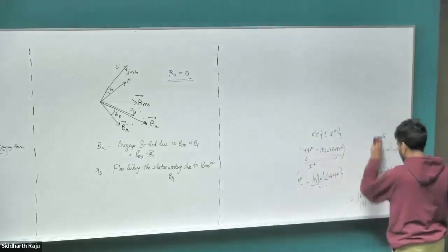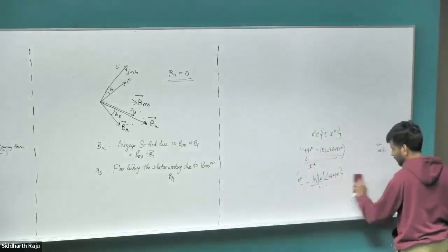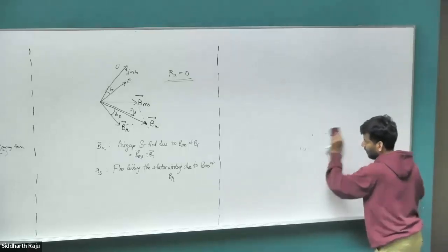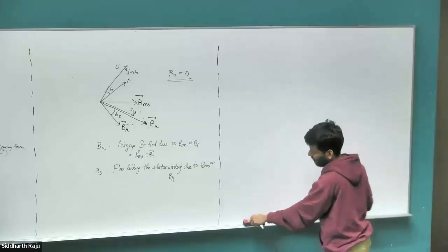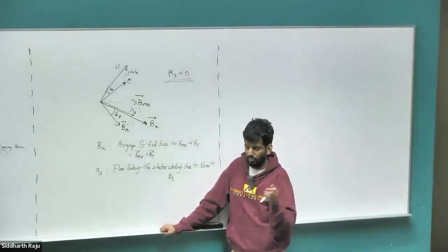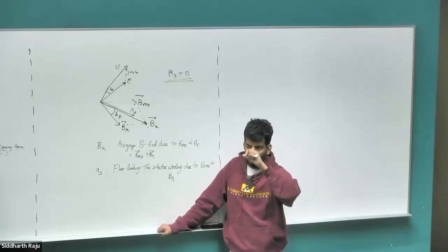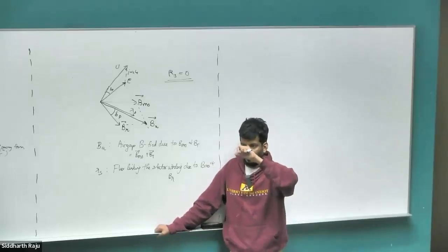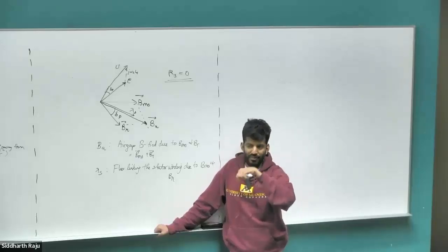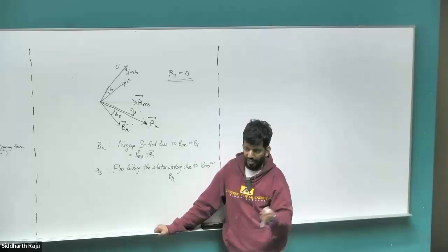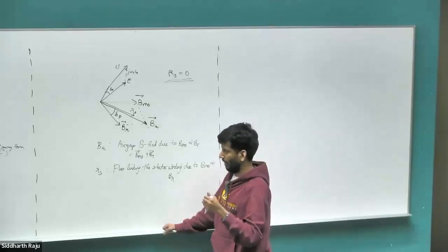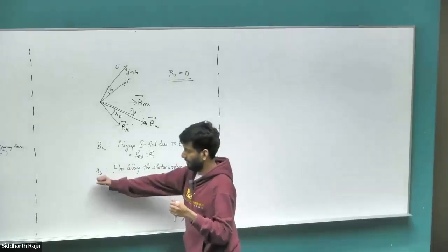And how do we go about deriving it? We basically looked at the magnetic field at every single point in the air gap, and then we looked at the conductor density that we are interested in, and we figured how much the B field is linking each of these coils. We took some delta theta, an incremental amount of conductors, and figured out the magnetic field that's perpendicular to it, and basically did an integration over all angles, 0 to 2 pi, to cover 0 to pi, to cover all the set of windings that are there. And that ends up giving us flux linkage.